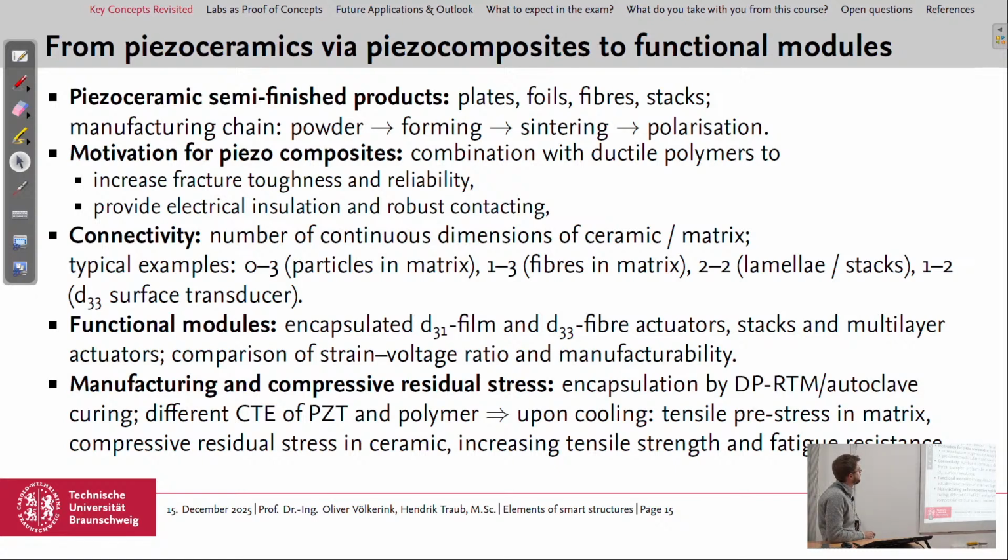Then we moved further on from the piezo ceramic over the semi-finished products to piezo composites and then to functional modules. We start with the powder, which we then form to the green body, sinter, and do the polarization.